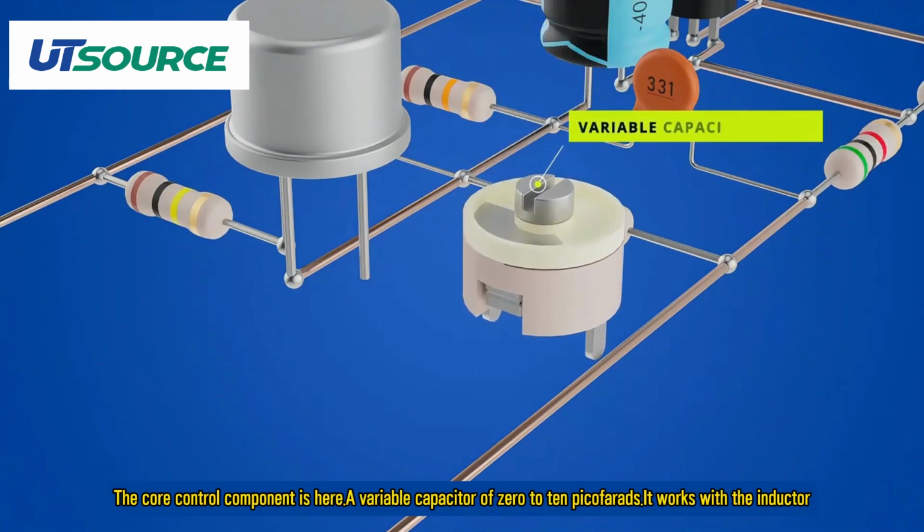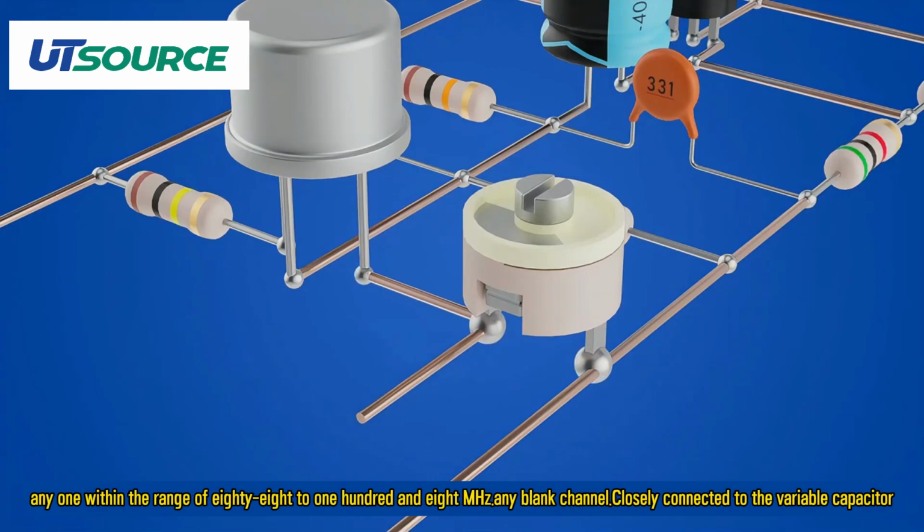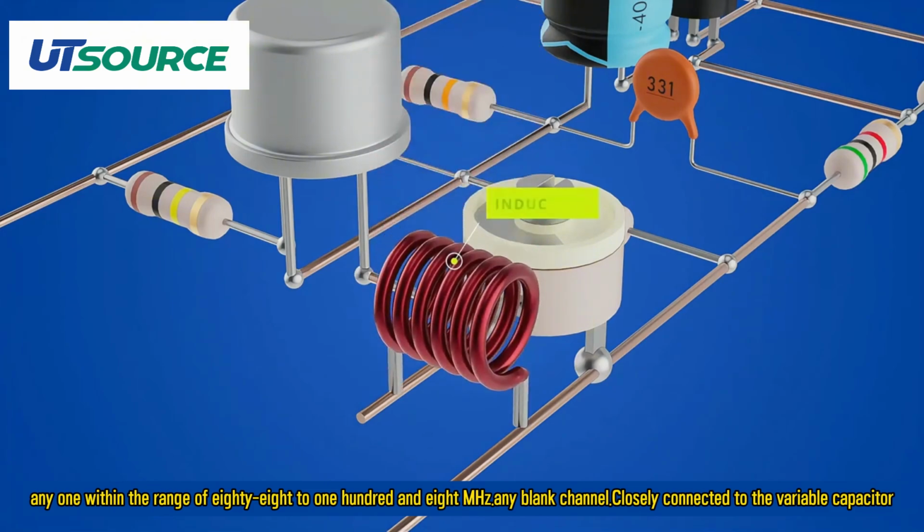The core control component is here, a variable capacitor of 0 to 10 picofarads. It works with the inductor and forms a resonance circuit that determines the transmitting frequency. Rotating it, you can precisely adjust the transmission frequency. Anyone within the range of 88 to 108 MHz, any blank channel, can be chosen. Closely connected to the variable capacitor is a